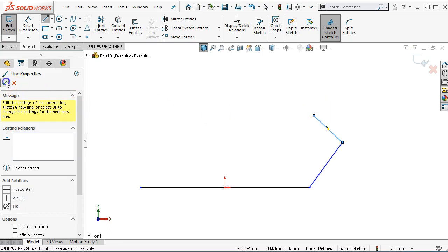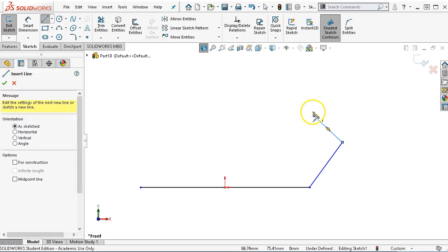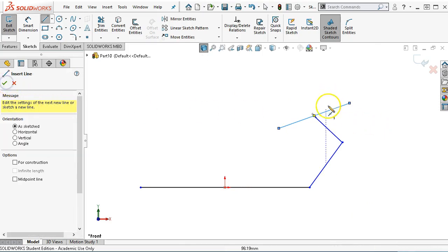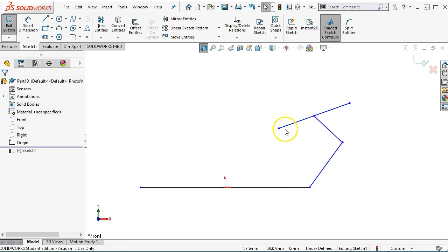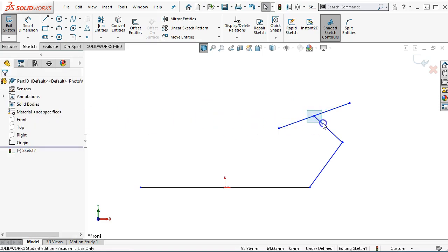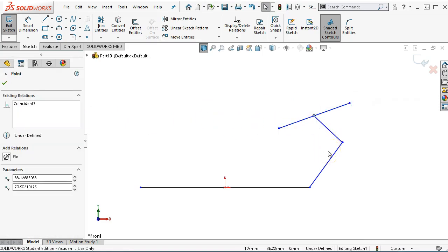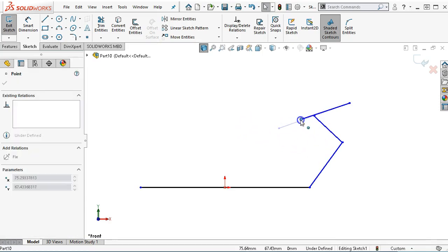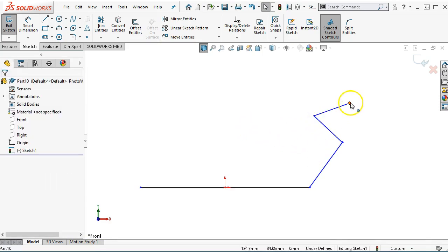So at any point that you click on the checkbox, even though midpoint line over here is not checked, the symbol shows me that I'm in midpoint. I'm going to get that back. To correct, I'm going to come over to the relation, delete the midpoint, but I still have that point location that it created for me, so I'm just going to window pick and delete that out, drag it back.